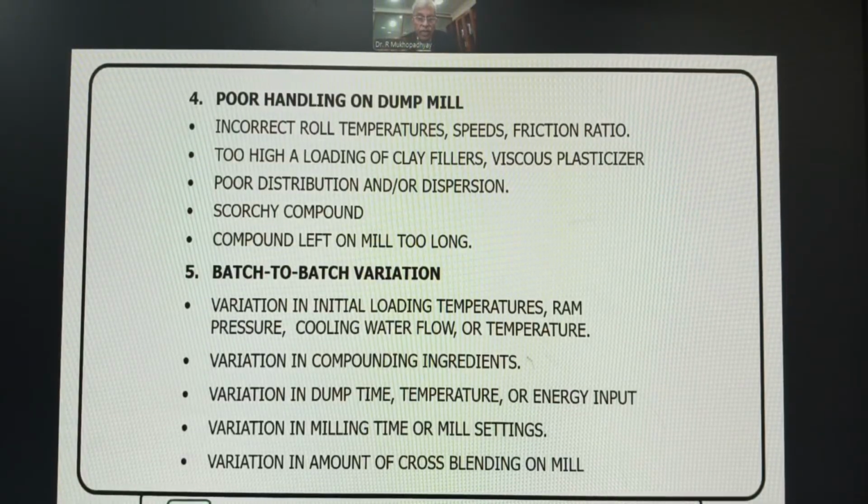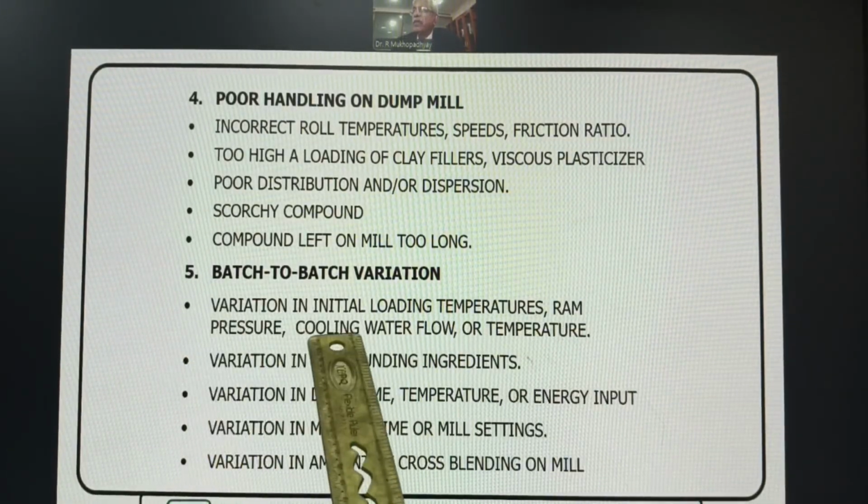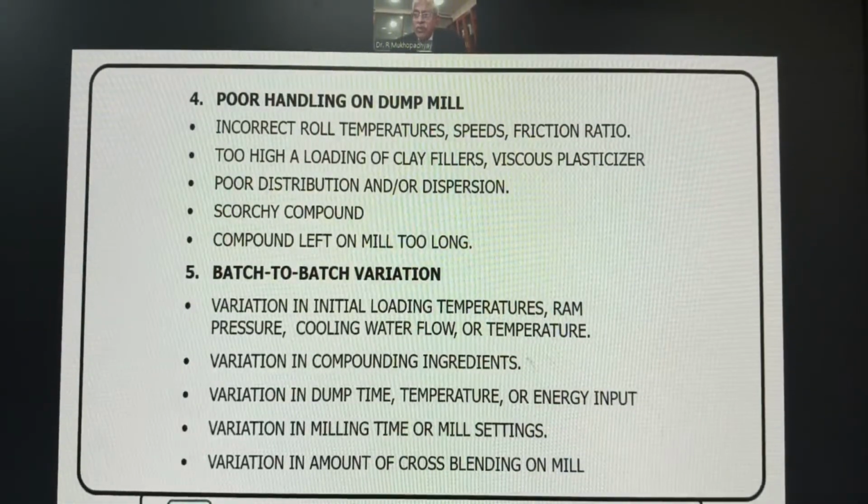Then batch-to-batch variations. These are the common problems all of you are aware of. There may be variation in initial loading, temperatures, ram pressure, and cooling. Generally what happens before loading the chamber of the Banbury, a minimum temperature is to be maintained in the Banbury.